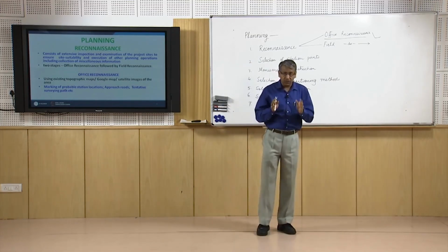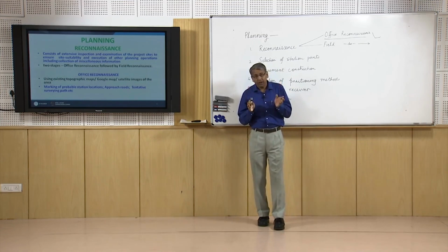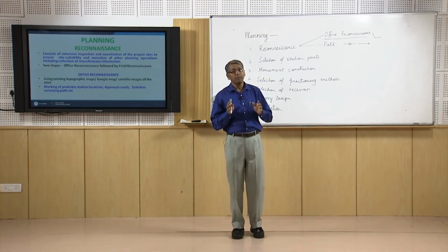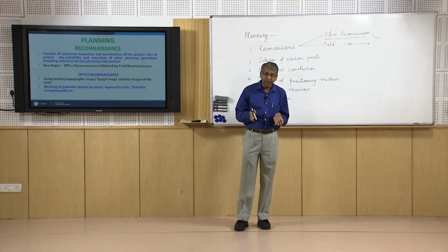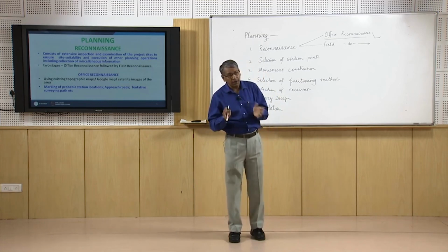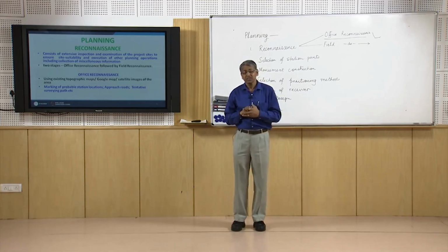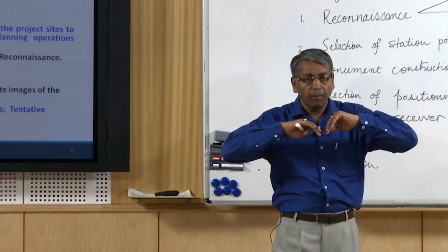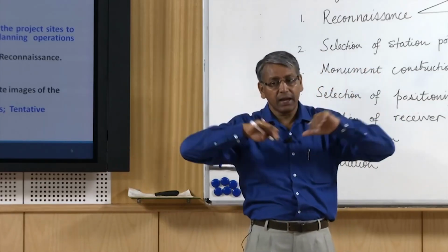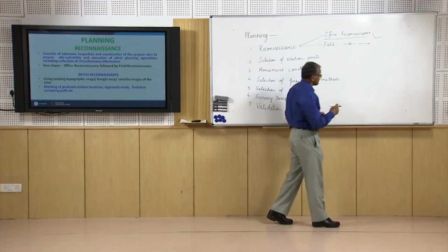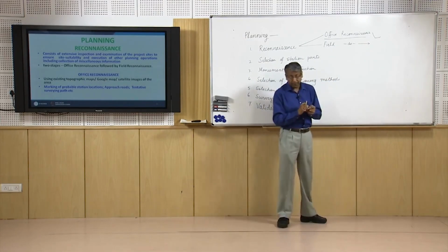Now, if it is suitable means whether the location is free from electrical interference or away from or devoid of any reflecting surfaces, and the station should be clear from physical obstruction at a cutoff angle of 15 degrees preferably. So, these are the primary things.